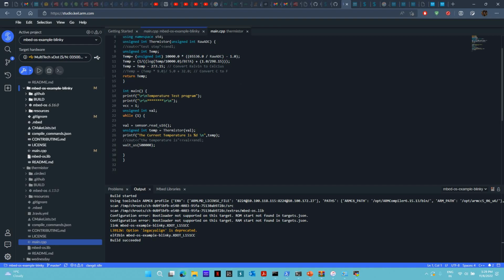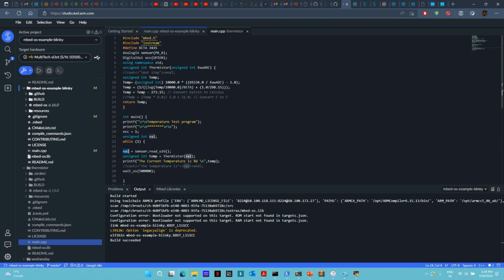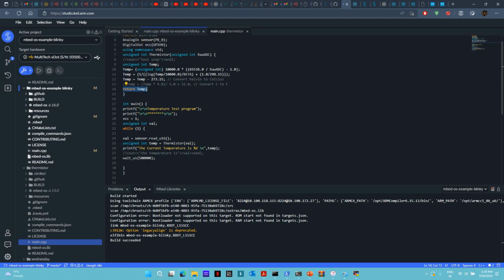We're going to get the digital input here in val, an integer, and we're going to put it into this function that's going to convert this digital value into a human recognizable temperature centigrade value. So we do these functions, and then we get the temperature in centigrade. And what we do is we print this temperature, and this is done every 500,000 microseconds repeatedly.